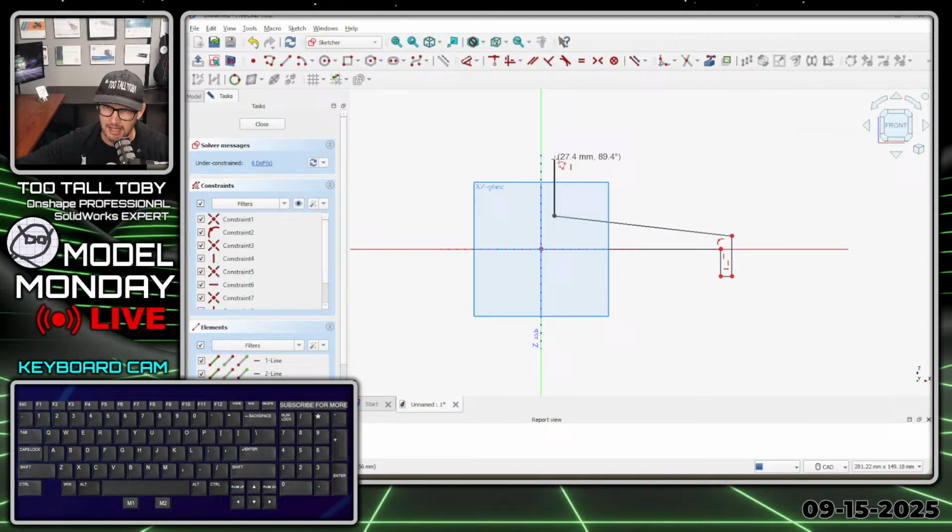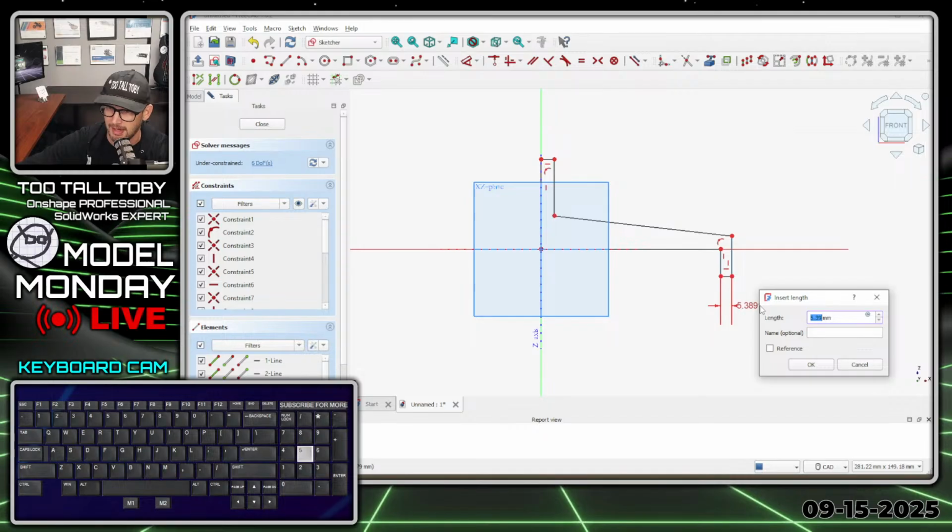This one's going to come straight up again, and then over here horizontal. I'm looking for that feedback letting me know that I am in fact horizontal and exactly on that plane. And then I'll close off this sketch like so. Now I'm going to press D, which jumps me into the dimension commands. With my dimensions, I start out with the smaller dimensions first.